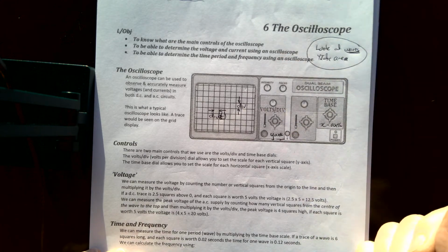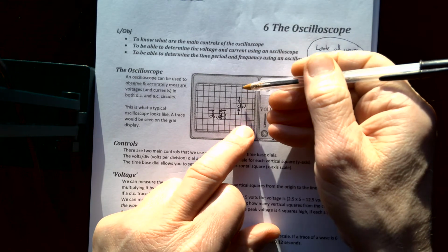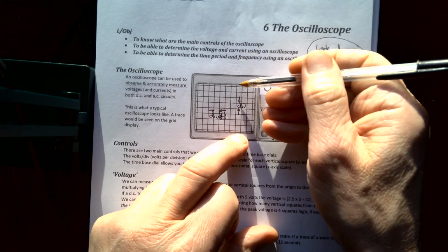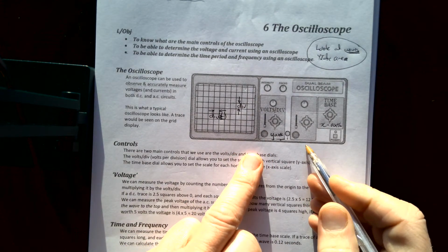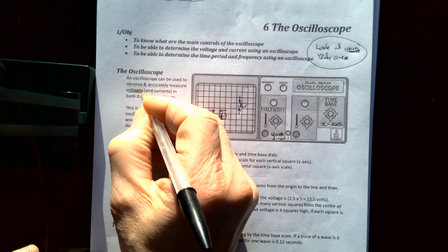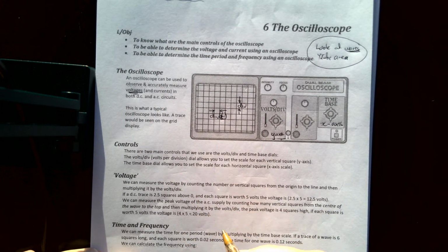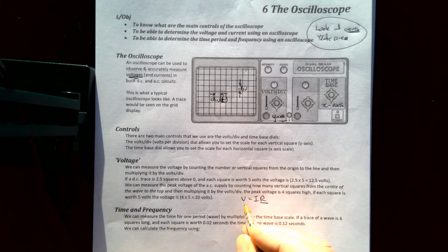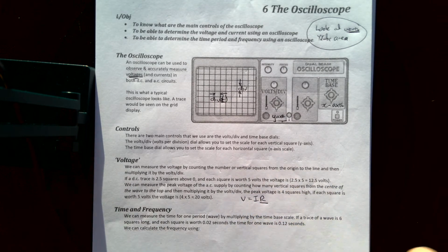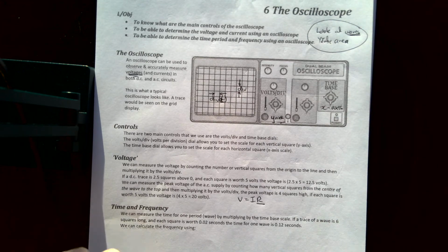Now, the crucial bit is that this changes the electric field that makes our electron go up and down. So it's voltage that this measures. This is a voltmeter. If you want to measure current, you need to use the idea that V equals IR. If you have a known resistance, then by measuring the voltage, you are measuring the current. You're just using a little bit of analogy there, and that's how all meters work anyway.